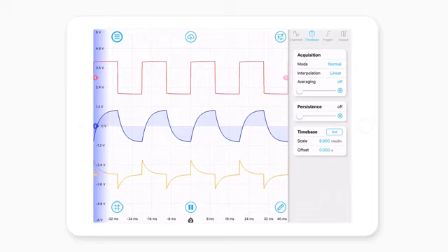Moving on, we'll have a look at the time base. So the Moku Lab samples the inputs at 500 megasamples per second, and this is very, very quick. The ADCs have a resolution of 12 bits, but we've included a mode that allows you to effectively average input samples when looking at lower frequency signals.